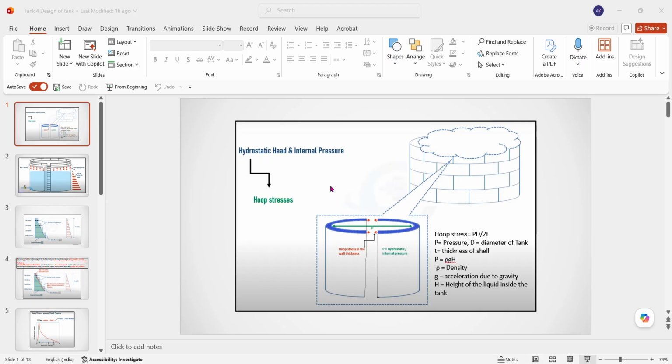Where has the 2.6 factor come from? We are doing the thickness calculation as per the 1 foot method, the 1 foot height method. So at 1 foot or 300 millimeter height from the bottom, how much will the liquid pressure be? It will be 0.433 psi.